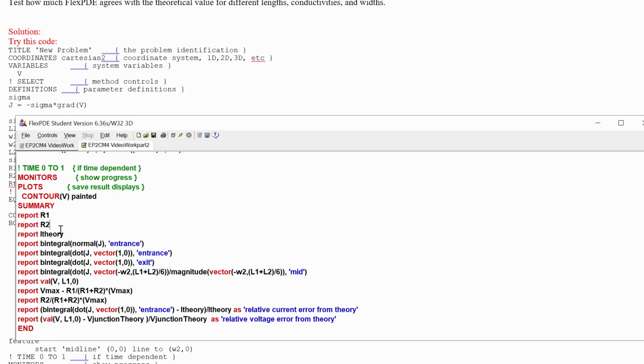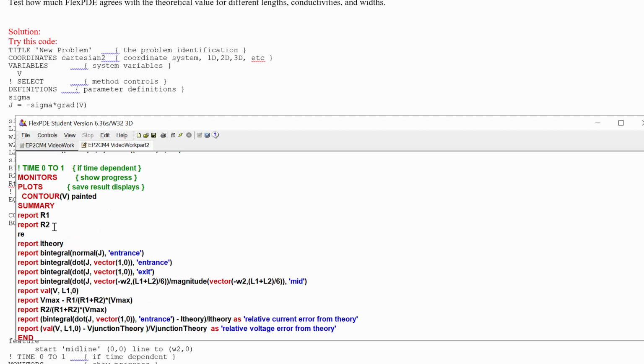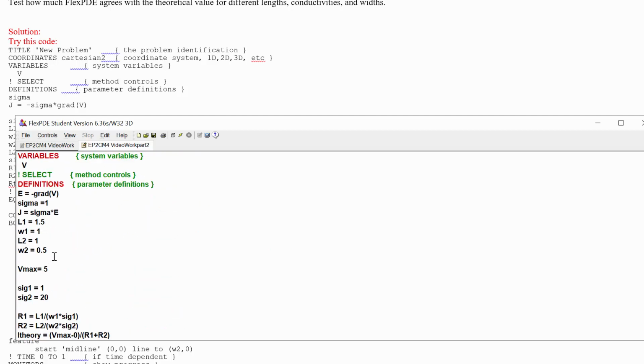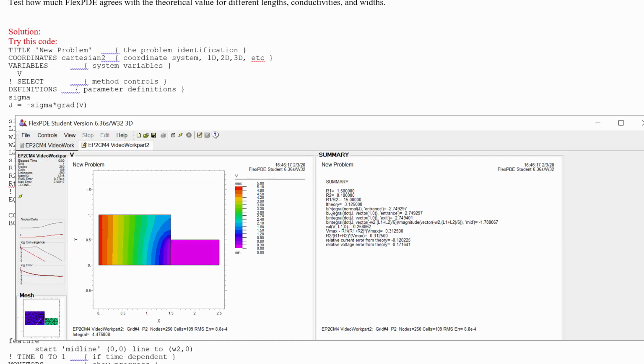Let's also report a ratio. Yeah. The length being 50% higher means it should be 50% more resistance. So 20 and then times 50% more is going to be 30 times more resistance. And then the width is half as much. So we expect 15 times more resistance. Let's check. Yeah, so 15 times more resistance for R1.